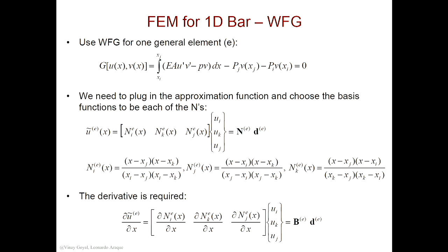And the shape functions are known. You know those functions, okay? That's what we did last week. And we realized that we had to calculate du dx. And so du dx is right here. So I took the derivative here, so I get N prime, N prime, N prime. That's what you see here. Repeated down here. And so now I'm primed to substitute this into my weak form Galerkin. And so I did that.